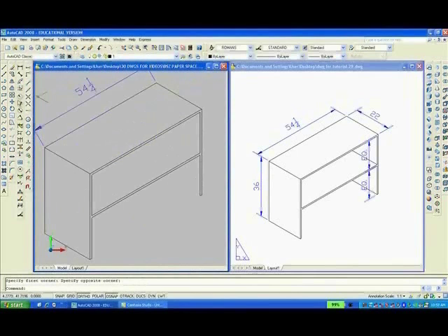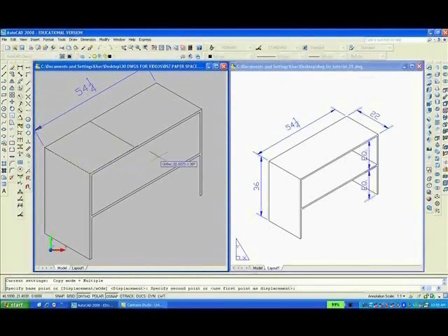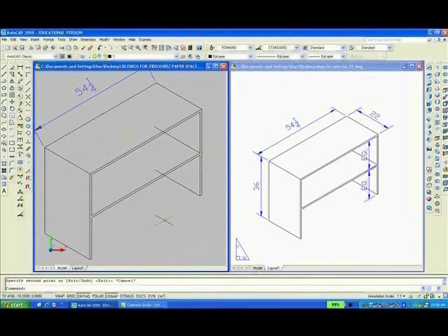Of course, to make the picture complete, we want to copy, let us say, any one of these side lines here. Copy that and put it here and put one here. Escape, and then we'll want to trim from that line and also from that line. Enter the excess like that. So for all intents and purposes, the picture is correct, and we have to finish dimensioning.